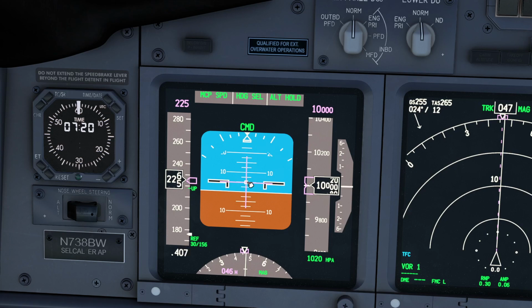Pretty much aligned. It doesn't need to be 100%, but you need to be somewhere there. If you have the flight director telling you to maintain a straight and level flight like it is right now, and you are banking like 25 degrees to the right, the autopilot will not engage on the real airplane. This is the first action for the real autopilot engagement.